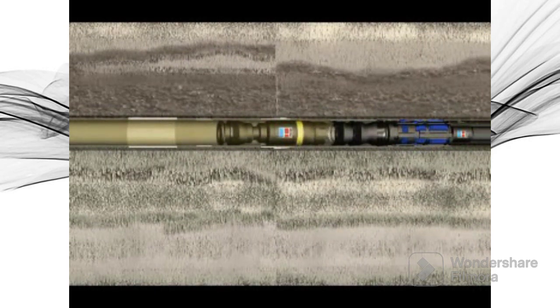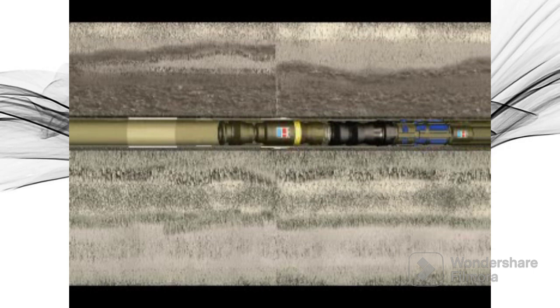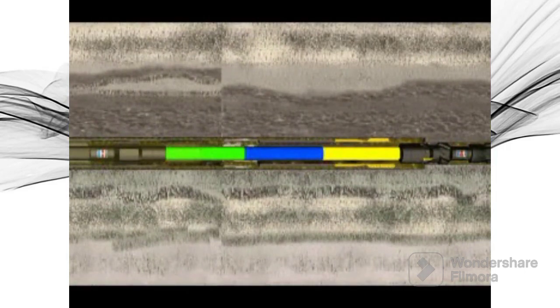Steps involved in directional drilling. The first stage consists of directionally drilling a small diameter pilot hole along a designated directional path. The second stage involves enlarging this pilot hole to a diameter suitable for installation of the pipeline. The third stage consists of pulling the pipe back into the enlarged hole.